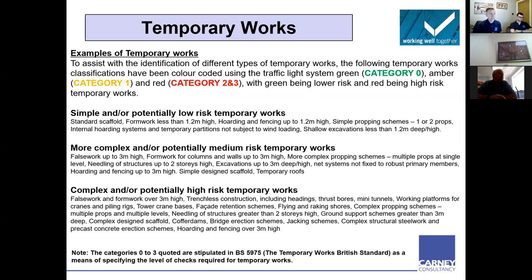Category 3 is an external verification. So basically, somebody designs said temporary works. It then gets passed to an alternative company with no communication at all. There's some drawings which I've designed. Can you please verify them? Make sure that the calculations are correct. We'll then review it. If they both marry up, brilliant stuff. They can crack on and go to site and be developed.